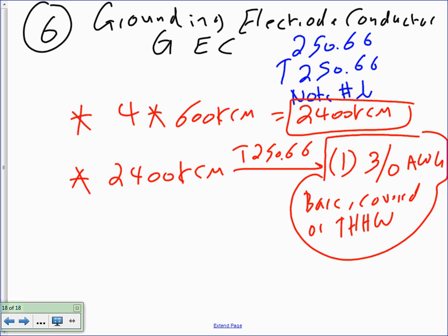Everybody knows the cover versus insulated. Cover just gives you cover to protect the material, but it's not rated to protect you from the voltage. If it's covered, it looks like insulation, but it's not rated to protect you from being electrocuted if you grab on it. It's just to protect the conductor. Bare, of course, is bare. And insulated is fully insulated to carry current. Your option for this will be either bare or covered.